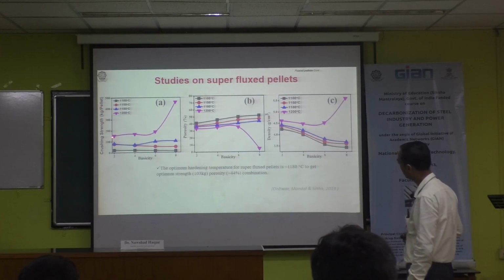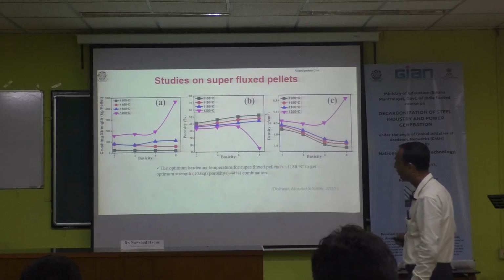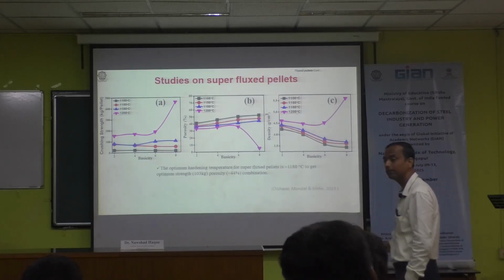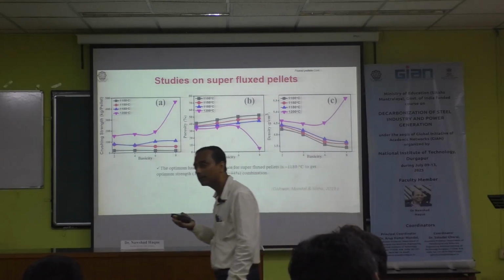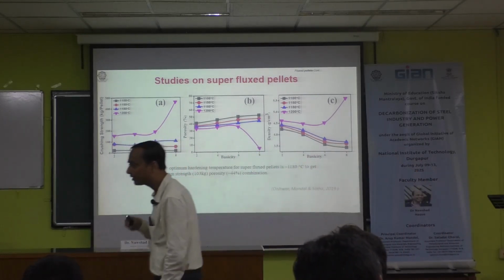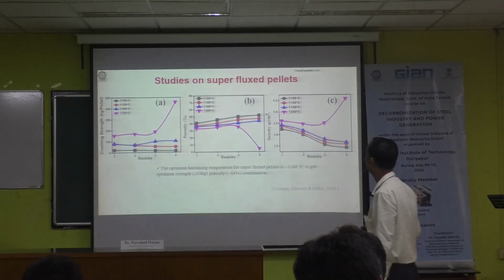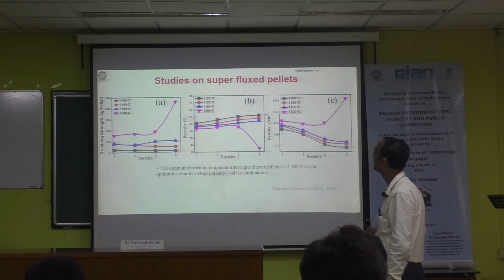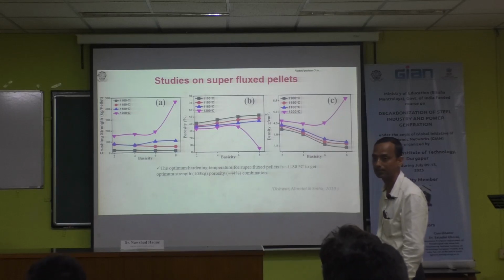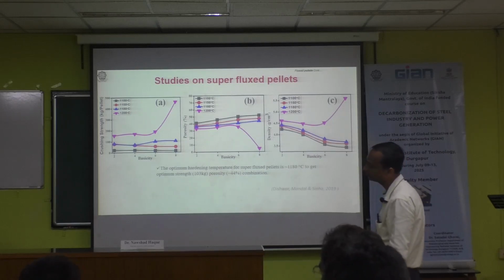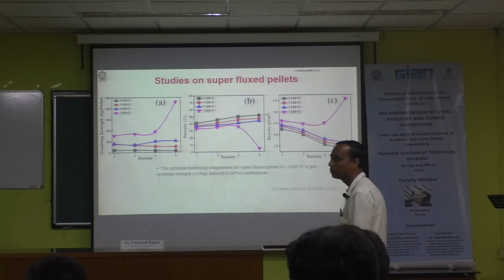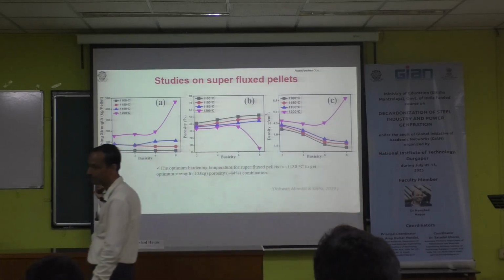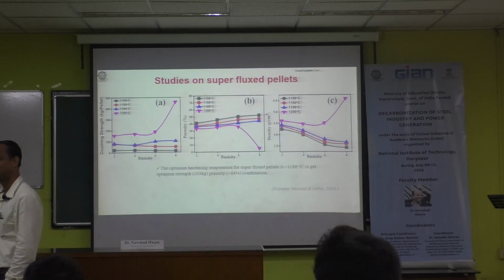This is the crushing strength step. You can see drastically it is reduced, because when free lime is there and there is no slag bonding, the strength is less. When it started production of this compound, drastically you can see the increment of the strength, CCS, of the products. The basicity is from 0.2 to 2.8, and how you can handle 2.8 is very difficult. 2.8 is too much.